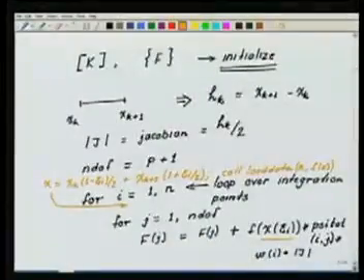At that physical coordinate, I take that value, pass it on to this load data routine, which should for this element return me the value of the distributed load at this point. That I put in here, multiply by the value of the shape function corresponding to this point into the weight function into the Jacobian. So, this is all I have to do as far as the load vector calculation is concerned.